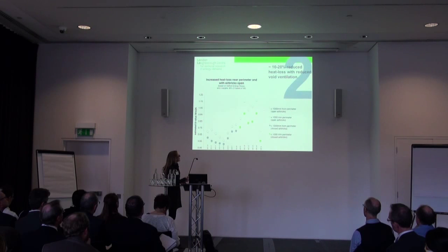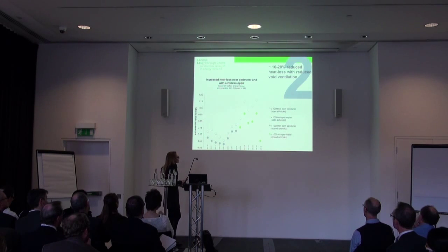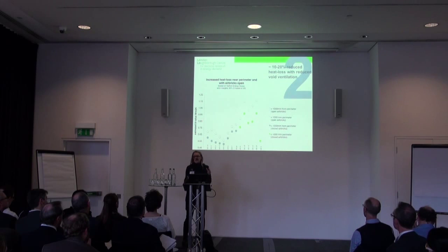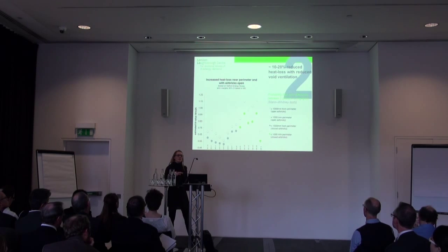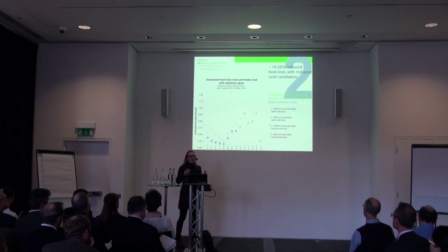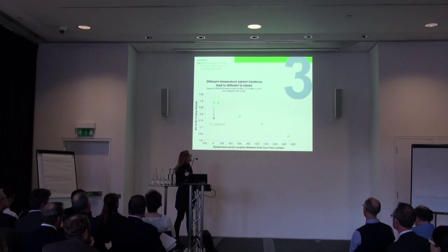The greater drops are near the air bricks, again what you expect. There's also less variation in heat loss when the air bricks are closed. This is also statistically significant. So the difference between the heat loss when the air bricks are open or closed also matters statistically.